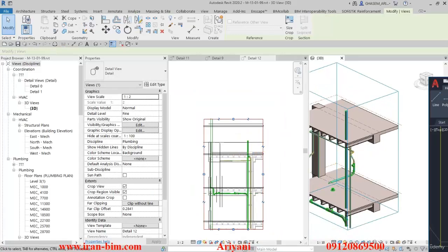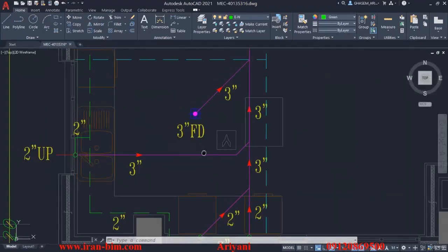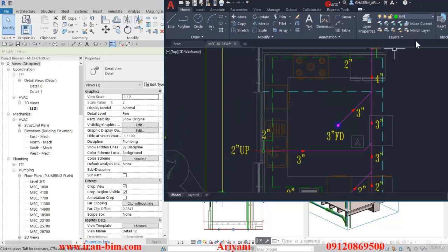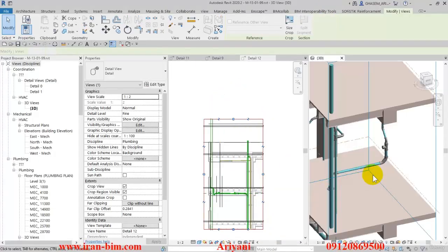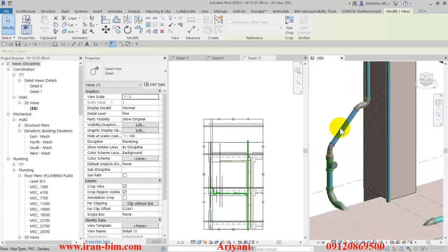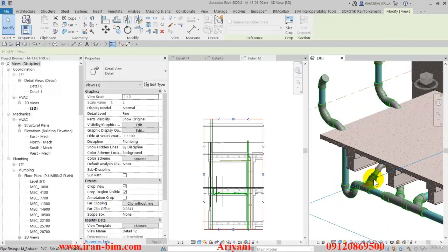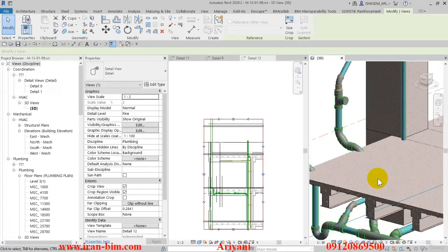So as you might know, the sewage system has to be completed under this strategy itself. And it has different parts, for example, one of which should be done using a 45-degree angle, like here, and in other places where we have some sinks, we'll create a vent from the point after the three-way fitting itself. And in places like this where we don't have any other way to go, we can put it before the siphon. Now, as I said, guys who are mechanics themselves already have a grasp of these elements and know what to do in these situations themselves.